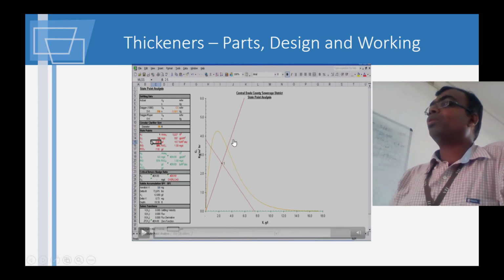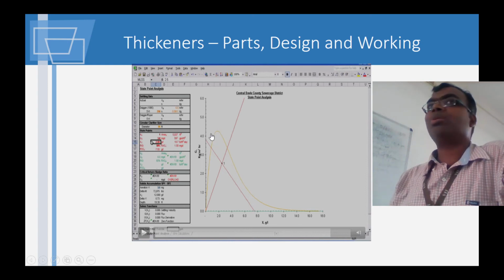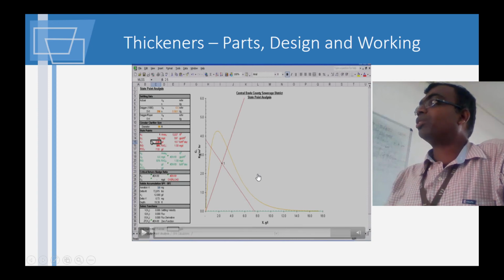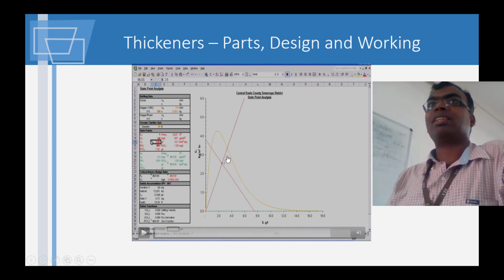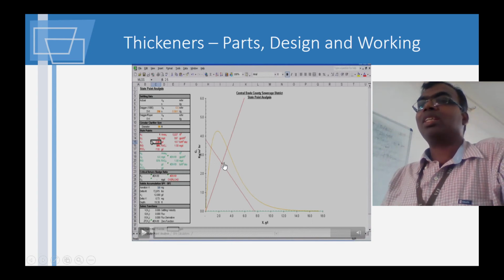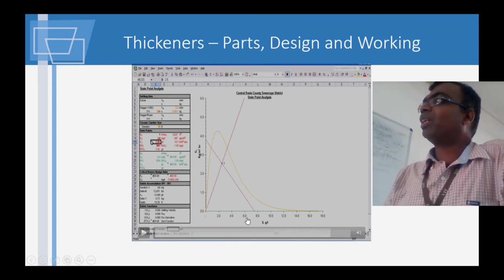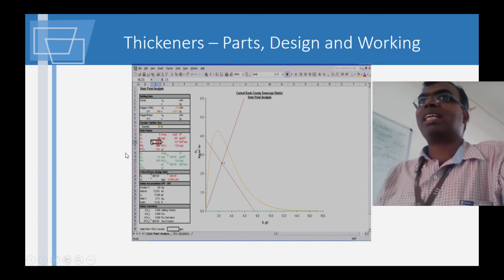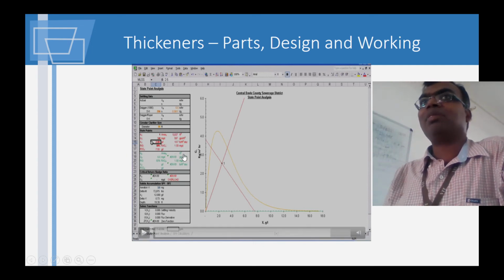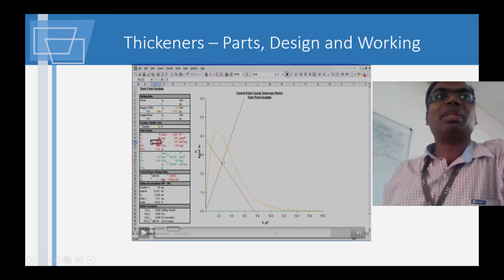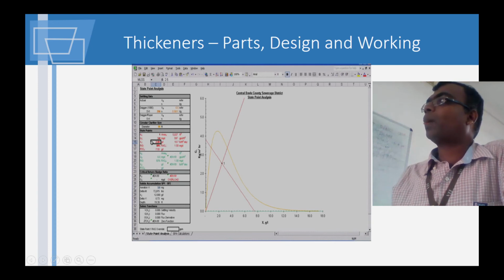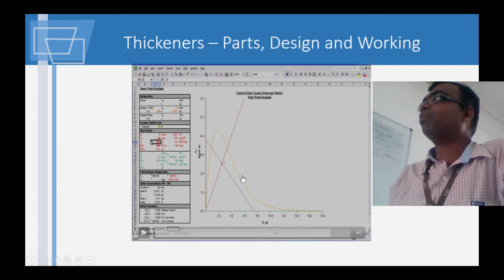So it is a relationship between a volume of sludge and weight thickening. Now you have two lines here. One tells you what is coming in and how it is going out. So this line, and then you are finding where the state is going to be present. So you can change the profile by modifying chlorine. That is, it means that you are killing some of the bacteria which could be there, basically what we saw a little earlier, the filamentous bacteria which can cause troubles in settling.